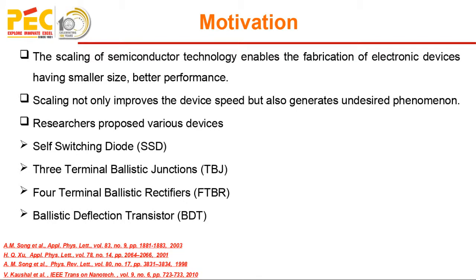So self switching diode is a 2-terminal device. When you apply the potential between the terminals, you will get the characteristic like a diode. The self switching diode is planar in nature. It has the capability to work up to very high terahertz frequency. Recently, 1.5 terahertz response of the SSD has also been proposed in the literature.